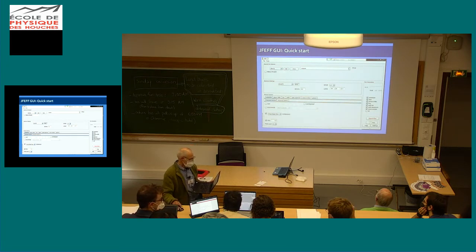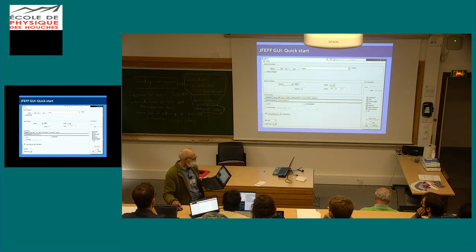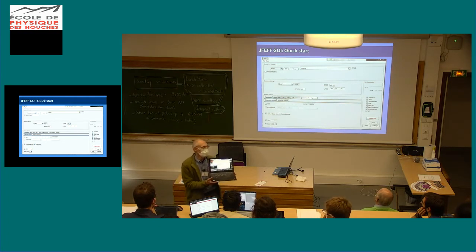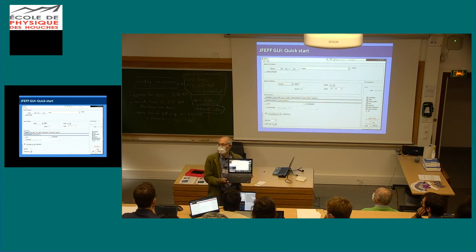Okay, so let's do this next example. So we go to File, and let's do Open Example. And we're going to do XANES. Click on XANES. We're going to do GeCl4, 5 atoms. So that should do that in about a microsecond. Open it. Okay, and if you do that, you should see that now it fills in all the fields for this molecule.